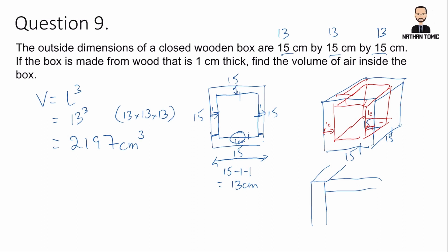centimetres cubed. This is a very common sort of question actually when you start building things, because we often talk about the outside measurement of something, but then we often want to put something into a box, for example. So you might say, yep, I've got enough space because my box is 15 by 15 by 15, and I can put this piece of whatever in, but then you don't actually have enough room inside because you've forgotten to take into account the thickness of the material that you are using. It's really about understanding that we had to take off a centimetre on either side of this measurement.